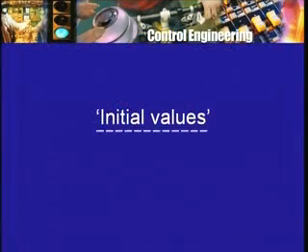They are sometimes referred to as dynamic variables for this reason, that is, their derivatives appear, not just omega m as a function of time, but its derivative occurs in the equation, not just Ia, but its derivative occurs in the equation. So for such variables we need to know initial values.